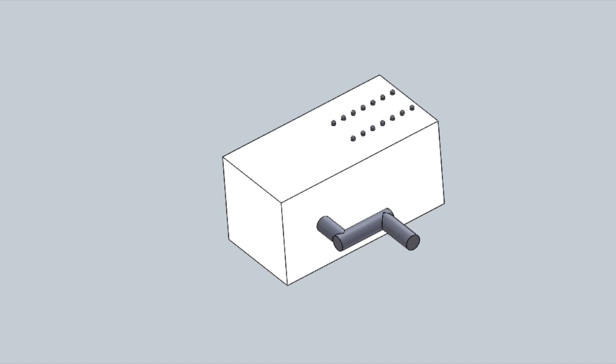Here's a visual representation of our device. Students will crank the handle, and as it spins, the LEDs on the top will light up. As the handle spins faster and longer, more lights will start to light up. The gear system and generator are located inside the box, and in the real-life model, the box will have clear plexiglass in order to show the user what is going on inside. Another possible addition to this model is to include a voltmeter, which will show how much power is being generated.